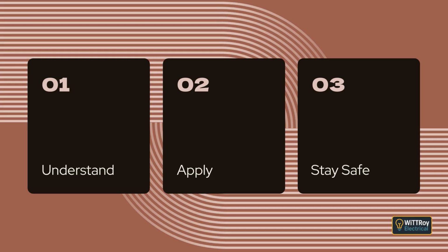Condition A. The device cannot be used to meet basic shock protection requirements. Condition B. After someone manually switches the device off, the automatic reclose must not be able to operate. This prevents accidental re-energizing during work. Condition C. A clear warning notice must be present, telling users that the auto-reclose must be disabled before doing any work, and reminding them to follow isolation requirements.